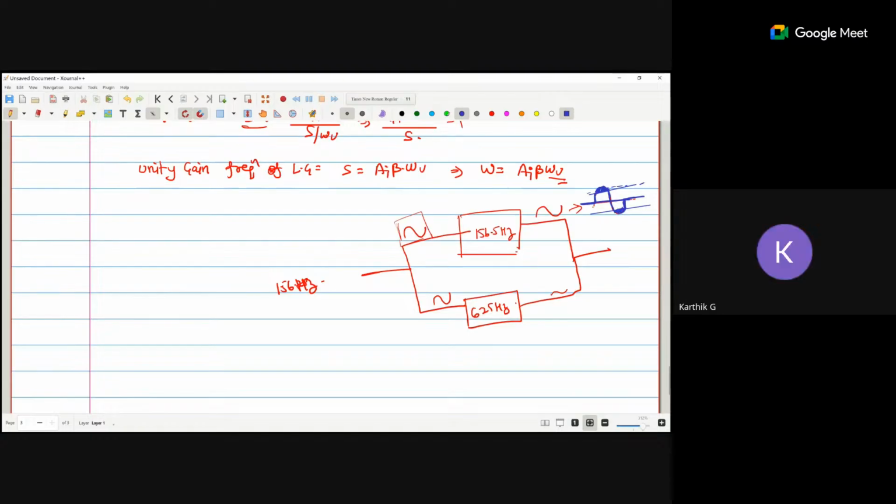That is when doing hands-on, sir. In LTspice, I'm getting proper sinusoidal waves, sir. But on the breadboard, the clipped one is coming, sir. So what particular resistor and capacitor are you using? I am just changing the value a little bit. I am not asking the value. Just change a little bit and check if you are getting any variation or not. Okay, sir. For 625 hertz, I'm getting the exact output as the input.